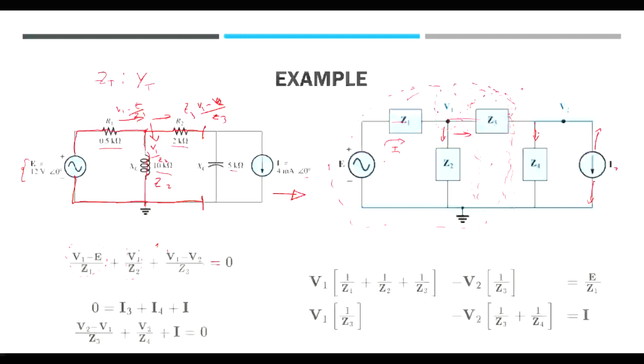And notice that so far, we can do a combination of equations so that even though we don't know any of the currents, except for this one that is given, we only have 2 voltage unknowns, V1 and V2. So we can set up the equation in terms of voltage. And that's what we're doing. We have equation number 1. And then for the second part, we know that, as we said, we can break the circuit from here all the way here, right?